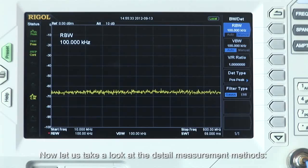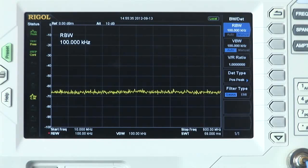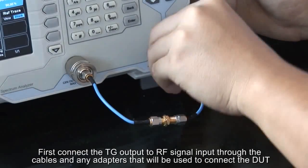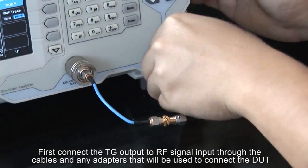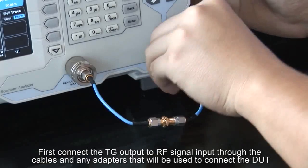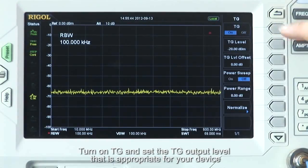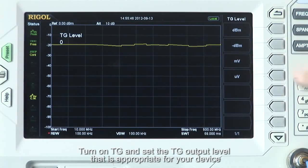Now let's take a look at the detailed measurement methods. First, connect the tracking generator output to the RF signal input through any cables and adapters that we'll be using to connect to the device under test. Turn on the tracking generator and set the TG output level that is appropriate for your device.